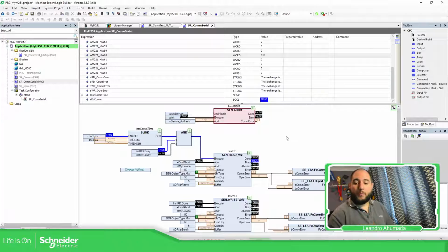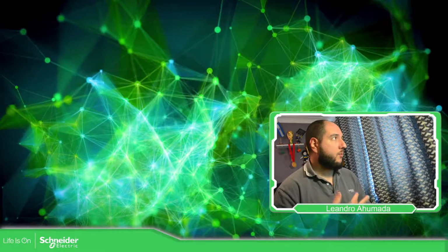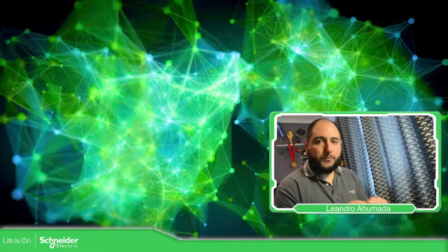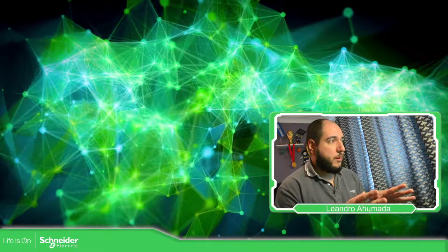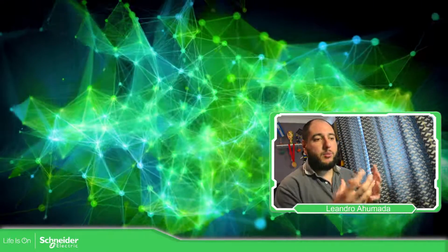So this is it for the Modbus serial communication using the M258, but it's going to be the same for the M241 or the M262. It's going to be exactly the same function blocks, the same configuration. So this is it for the moment, okay? Then we're going to see later how we can improve this and encapsulate the communication.